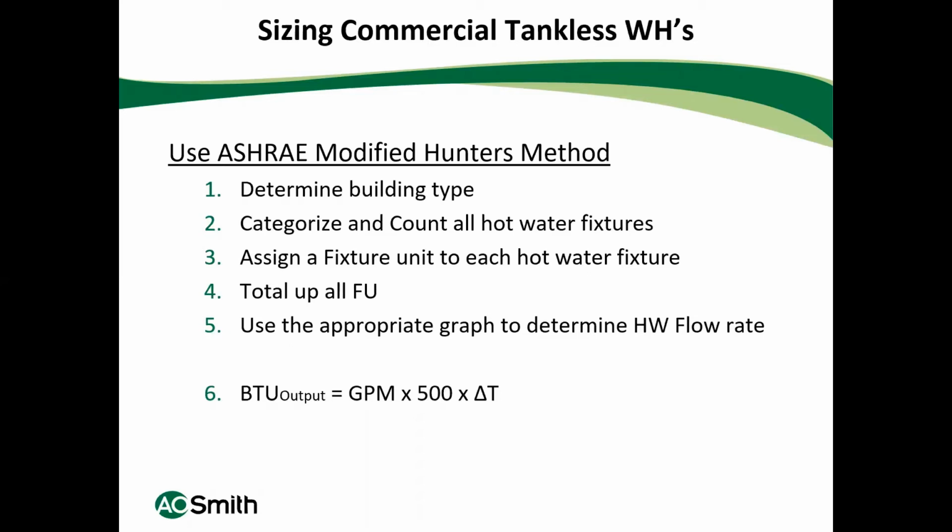You can change that if you want. If you only want your tankless water heater set at 120, you can change that. But your BTU input will change a bit. So the BTU output, I put that in there because some of our products are different efficiencies.